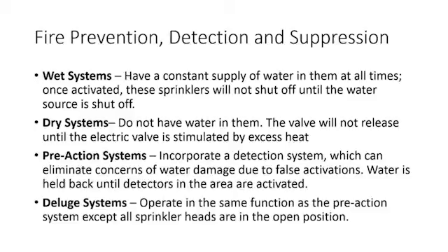They have a constant supply of water in them at all times. Now, once they're activated, the sprinklers are not going to shut off until you go shut it off at the main, right? It's not like it's just going to blast for about 5 minutes and be done, or blast for a minute and be done. These are connected directly to your water main in your facility. So you're going to have to shut that off, crank that wheel to get those to turn off.